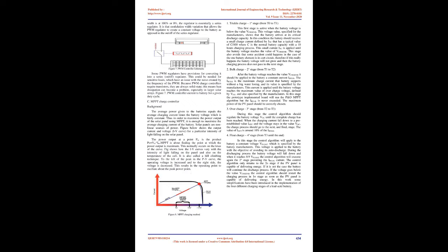The advantages of charging at constant voltage are that it allows cells with different capacities and different degrees of discharge to be charged. The large charging current at the beginning of the charge is of relatively short duration and will not harm the cell. At the end of the charge, the charging current drops to almost zero because the voltage of the battery becomes nearly equal to the voltage of the supply circuit.